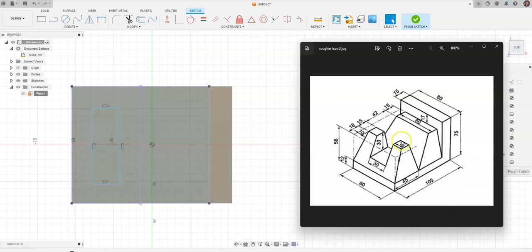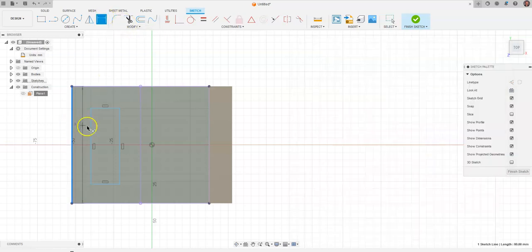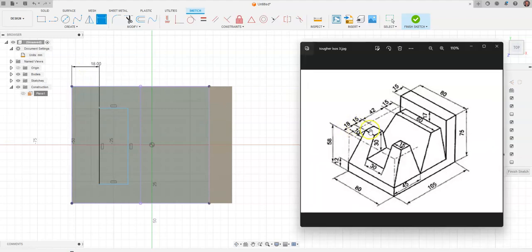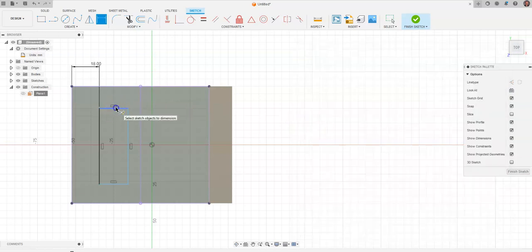We're going to use some location dimensions to help it, not size dimensions. So we're 18 in from the side. I can grab dimension from here to here is a distance of 18. I'll go 18. We go back over here. The width is 15. 15. Hit Enter.